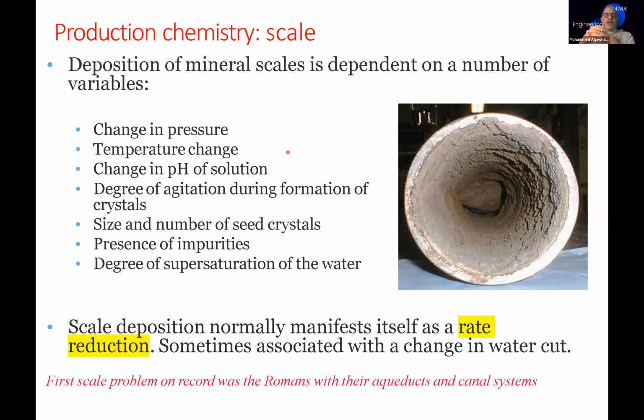This will cause, in the end, scale deposition inside the wellbore or the reservoir. So we need to consider these factors very well. We need to have a close focus on what type of water or fluid is injected inside our wells. When doing remedial action for any well, what type of chemicals are we going to use? Otherwise, we may, as a side effect, cause scale deposition.